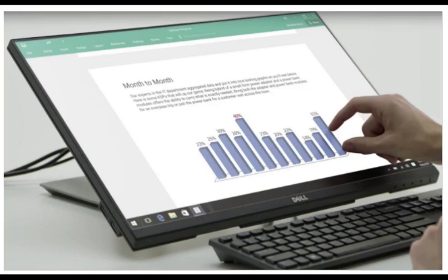Infrared touch screens use a matrix of infrared beams, which are transmitted by light-emitting diodes, LEDs, with a phototransistor receiving end. The infrared beam is blocked when a finger or tool is used near the display. This interruption provides the device with input on the location of the finger or tool.